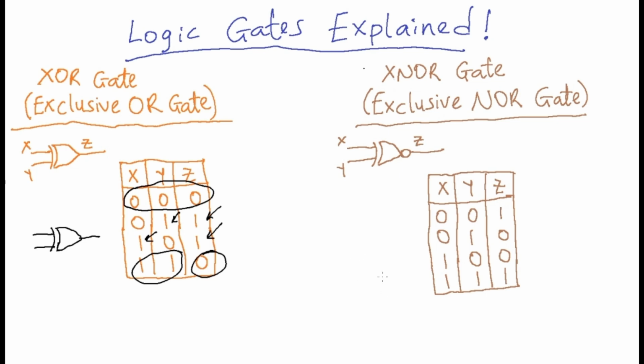Now, our XNOR gate is seen as an XOR gate with a bubble in front of it. So, taking a page out of the NAND and NOR gates, it can be modeled as an XOR gate that is being fed into a NOT gate. So this is our XNOR gate if we break it down further. But once again, for simplicity's sake, you just put a bubble in front of an XOR gate to represent the XNOR gate. So to make things very simple, just take it like this: an XNOR gate is just the output of an XOR gate that is inverted.